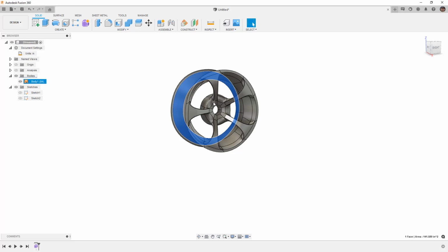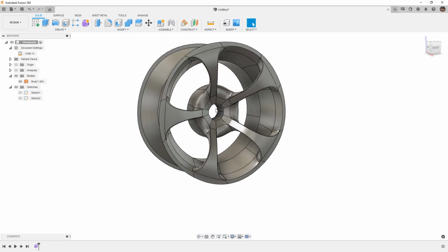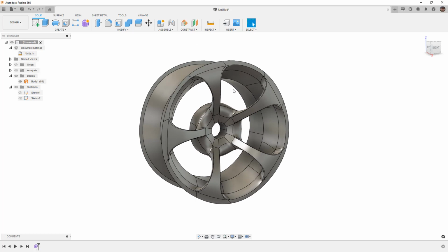We could create the perfectly revolved center hub section, and then we could simply create some surfaces where we want those to attach. It could just be a hole in the side of the rim barrel surfaces, or it could actually be some sort of extension that we attach to the edge and use it to control tangency. But either way, it's fun to explore this type of modeling with forms because this is much harder for us to do in a lot of cases when we're trying to use a typical surfacing workflow.